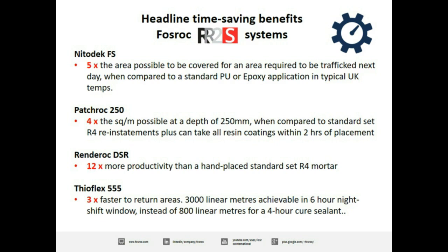over the top. DSR, 12 times more productive than the hand placed standard step mortar, and again gaining that rapid return to service benefit as well. And then finally we looked at the Fireflex 555, which can do, as we mentioned, 3,000 linear meters in a night shift instead of the 800 meters that you traditionally get from a 4-hour cure sealant.